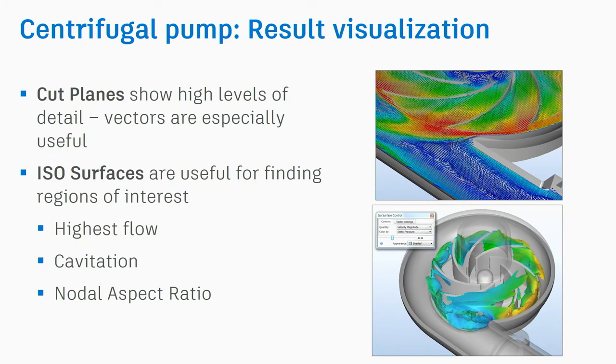For isosurfaces, if you define here, for example, the quantity velocity, you say, okay, I'm going to see the isosurfaces for the value of 4,000 millimeter per second. For isovolumes, you have an interval, a minimum and a maximum. I want to see the isovolume between a range.